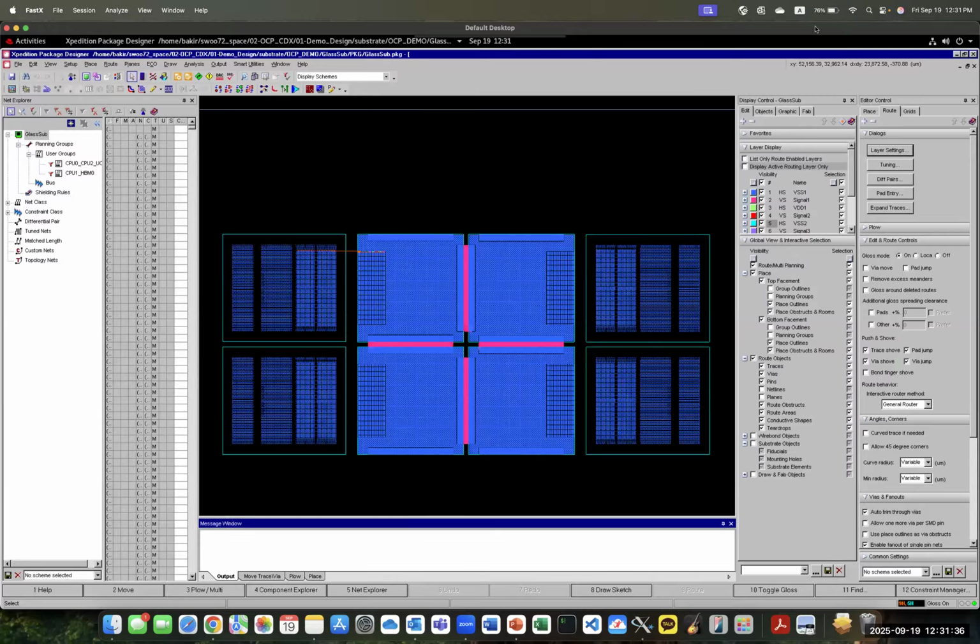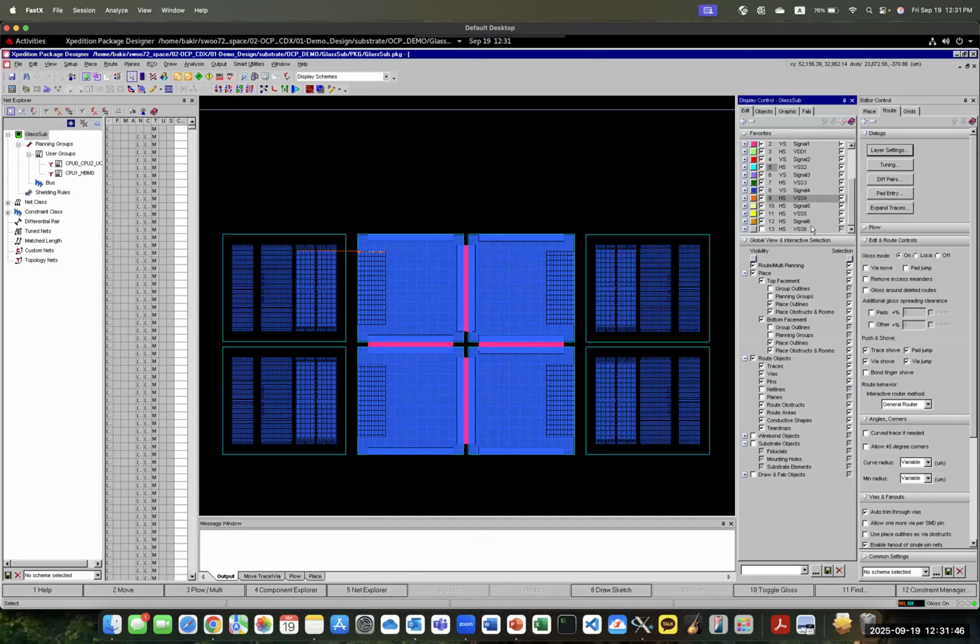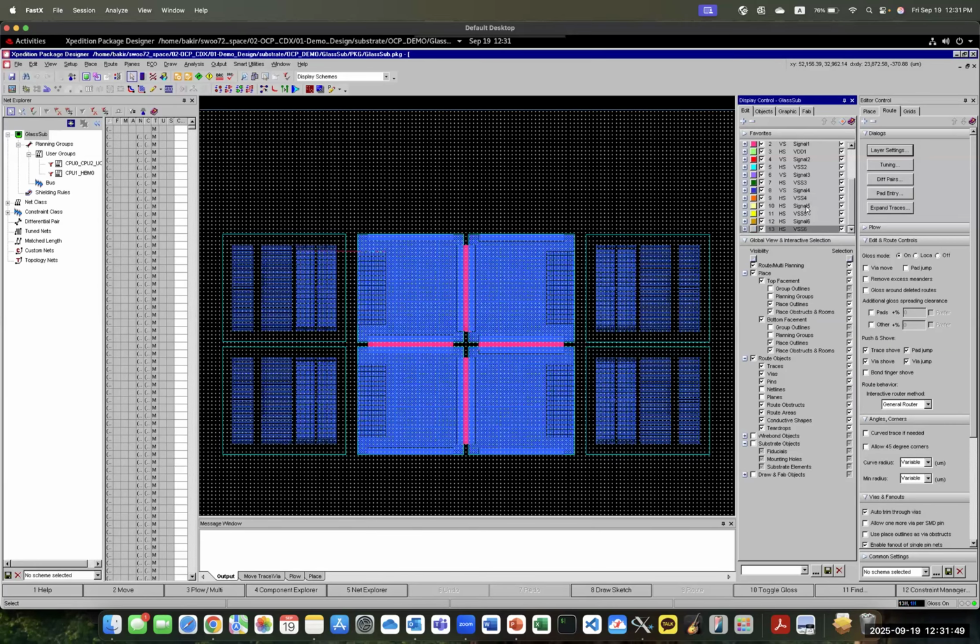I think putting the VRM on the bottom of the interposer for now is going to be fairly representative of, or similar to, putting the VRM in the substrate below, right? Yes, about the same thing. The idea is to show any benefit of current reduction, power reduction.